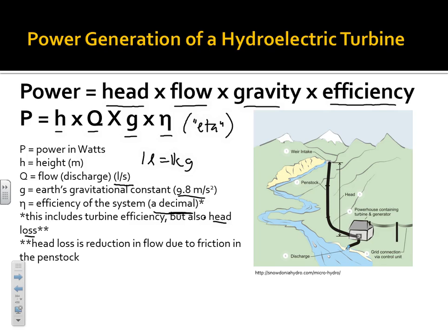When you do a calculation, which we're not going to do, when you're designing a system, you actually have to look at the size of your penstock. So if you're using a microhydro system, like a 4-inch PVC versus a 2-inch PVC or whatever, you have to look at the size or the diameter. You look at how long it is, and you also have to look at how many twists and turns or elbows you put in it. But anyway, for our purposes, we're going to assume a certain number.